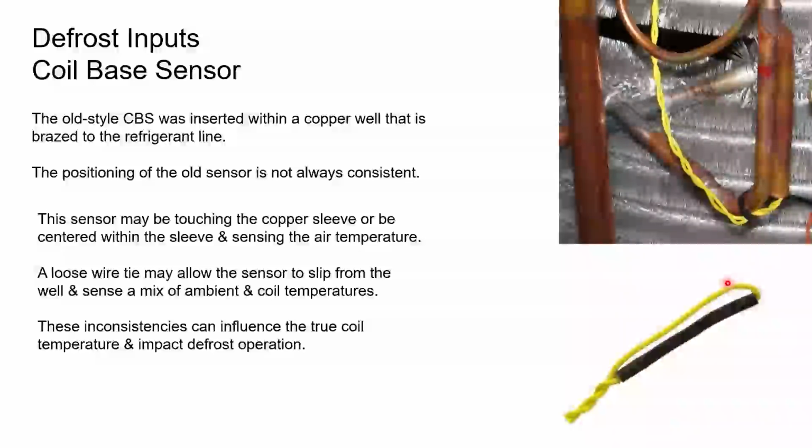The other thing that would happen is, again, these units are built by people. People make mistakes, and they'd pull that wire too tight, and it would cut into the sensor wire on that tubing edge. Even though you can see it's flared just a little bit at this piece of tubing right there at the bottom next to my red dot, it would still cut through over time. The other thing we'd have happen is, you see how this sensor is shaped with the wire that comes down across the back of the sensor.